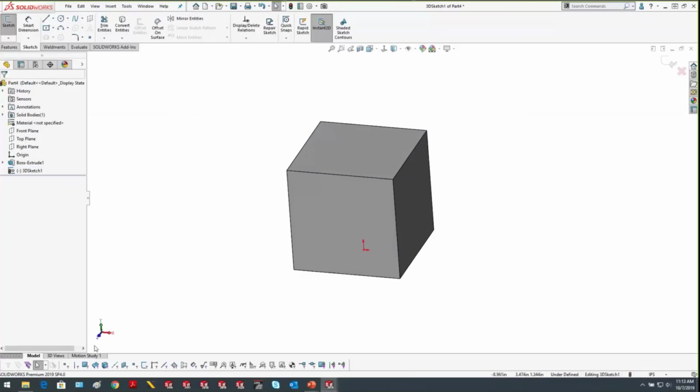And with the selection filters toolbar, there's a lot of different filters you can use. They're kind of being cut off by the screen, but we have filter vertices, filter edges, filter faces. So in this case, what I want to choose is filter edges. And I'll show you the hotkey for this. The hotkey for this is E. And I'm going to turn on this filter edges.